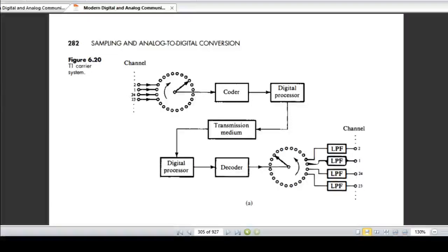When a large number of PCM signals are to be transmitted over a common channel, multiplexing of these PCM signals is required. So the basic time division multiplexing scheme called the T1 digital system or T1 carrier system is used. This system is used to convey multiple signals over a telephone line using wideband coaxial cable. The diagram of the T1 carrier system is shown here.